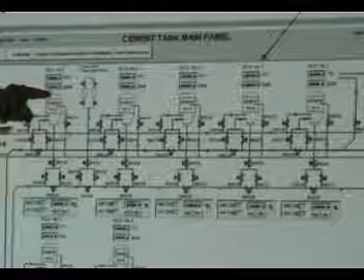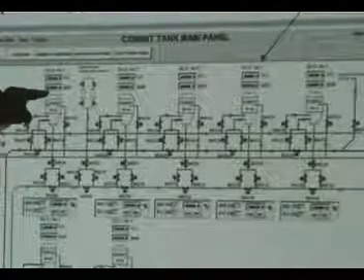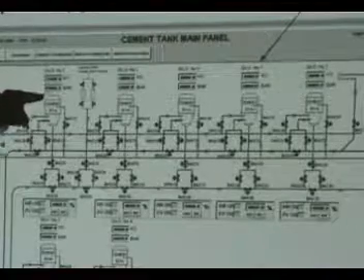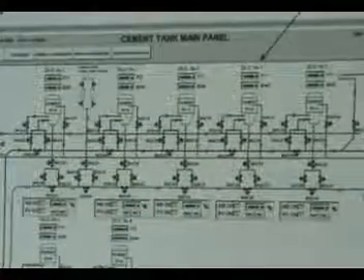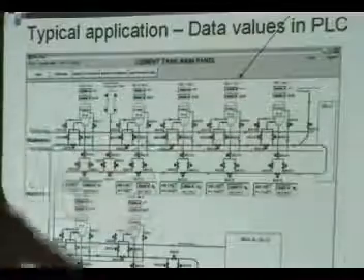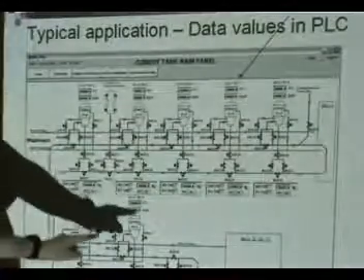And here, it's another one, and it's actually bar, BAR, and it's looking at pressure. So it's looking at the actual air pressure in the system and displaying it in this area here. And this is for every silo. And there were like 18 of these on the rig. So we're weighing the material in each of those. So all of these are data registers that are holding all of these values in here.